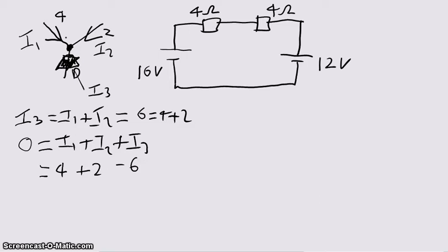The second law applies to a circuit like this one. It says that the voltage applied to the circuit is equal to the voltages that are dropped across each component as we go around the circuit. So you see this one plus this one plus this one, all added together equal the 16 volts. And this applies to any loop in a circuit. Even if you have other connections that come off here, it's still true that the voltage around the loop is equal to 0.